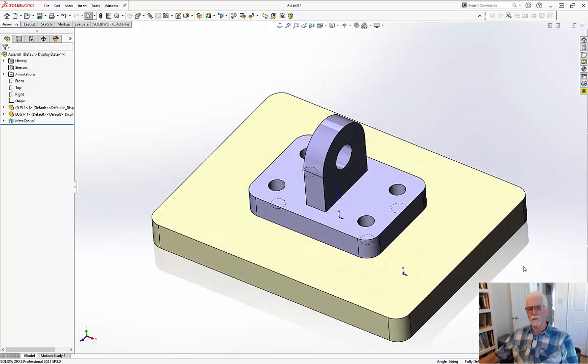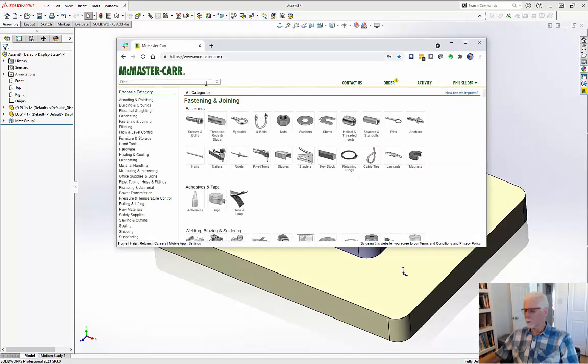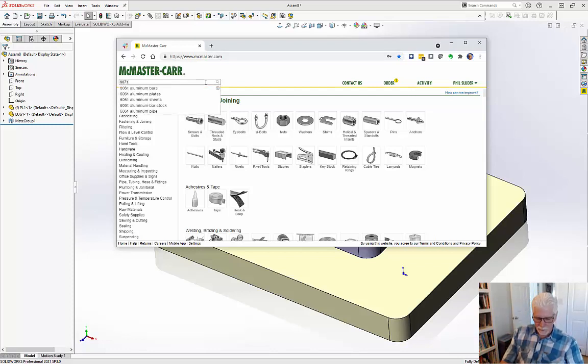Okay, so there's just a couple more things I want to show you. And I noticed I started all this with templates. So if you've got that luxury, it's worth setting them up. Okay, now let's bring in some McMaster-Carr parts. So let's bring up, we'll search McMaster-Carr. And we want 2 components in this for McMaster-Carr. So they are, of course you'd have to search and all that to do this properly, but I've already done the work. 6071K65.